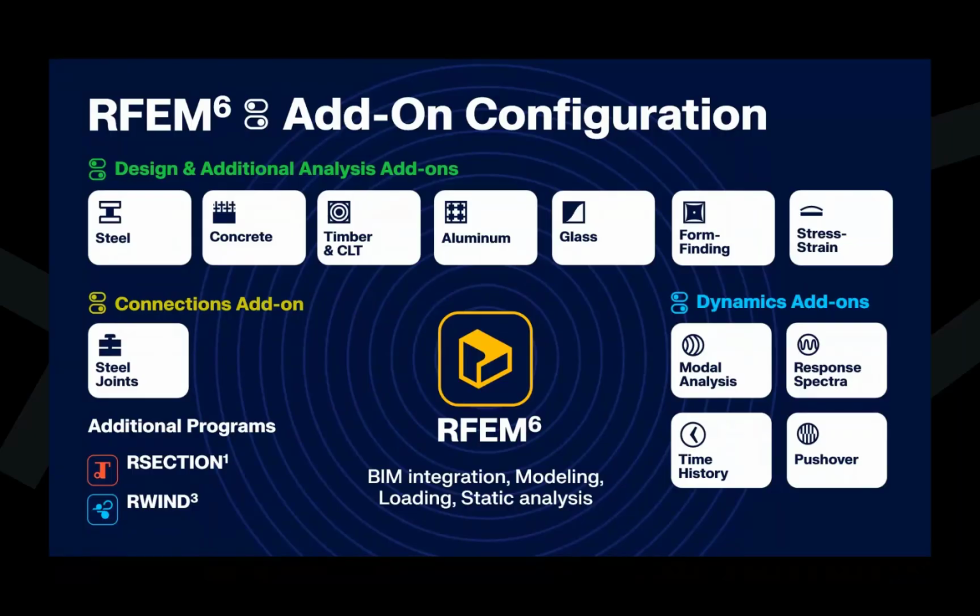For anything that requires a more advanced analysis, like dynamics for example, or if we want to carry out the design according to the various standards, we would need these individual add-ons. Just to name a few, you can see these listed here. This isn't an exhaustive list, but we will dive into some of these in just a few minutes. More or less, you create a software package that's specific to your design needs, beyond the general static analysis here. Now, we have a couple of standalone programs as well, RSECTION and RWIND. These we'll also touch on. They do integrate with RFEM 6.